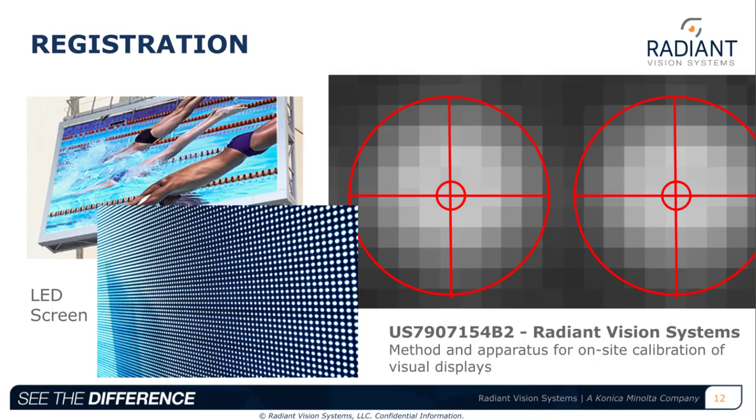The ROIs were aligned to the measurement system's image sensor array. We had many image sensor pixels across each LED display so that restricting the ROI to be centered on sensor pixels resulted in a region of interest that captured only the measurement data on the LED of interest and didn't include any information from neighboring LEDs.